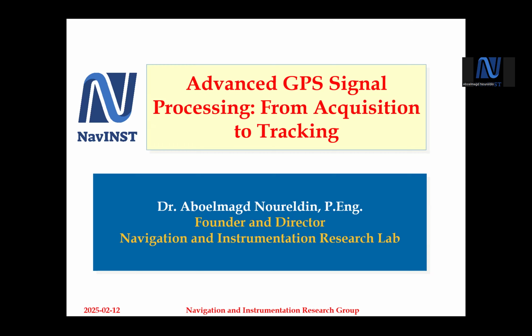We work on them to generate the high level measurements that are the range and the Doppler, sometimes also what we call accumulated range. Using those steps, we can retrieve the received GPS signal and extract key information for computing position, velocity, and time information.